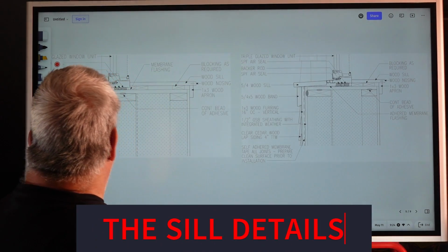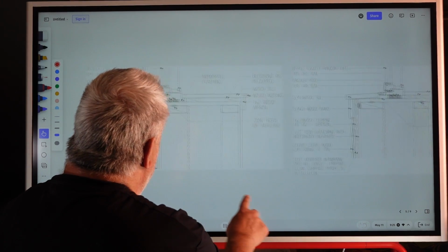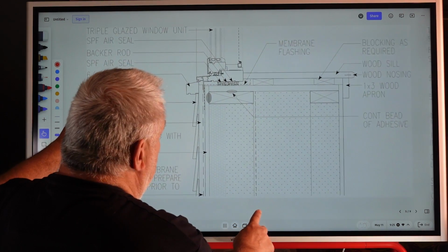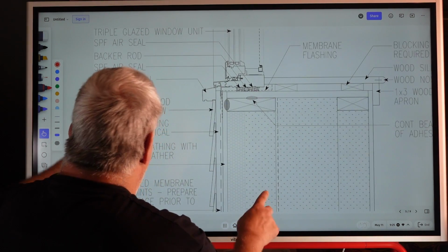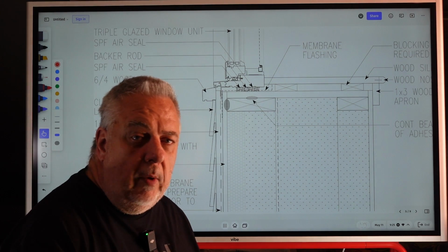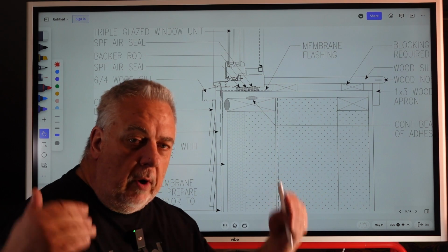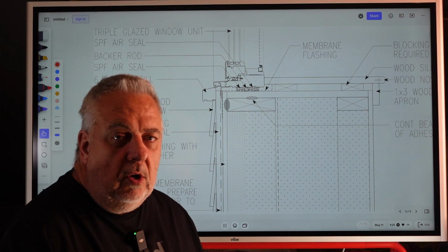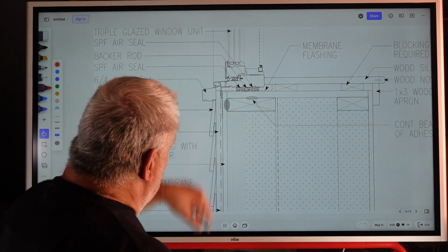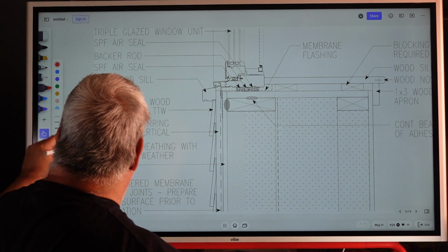But here's the windowsill details. And we'll start on the lower floor, because the choice was on the lower floor to do the outie, and then as we moved up, we pull the window in. I wanted to get upstairs, we had the shake, if you remember the photo, and I wanted to get those shakes to turn the corner nice and neat. And then downstairs, we would have all of our trim and window in the same plane.